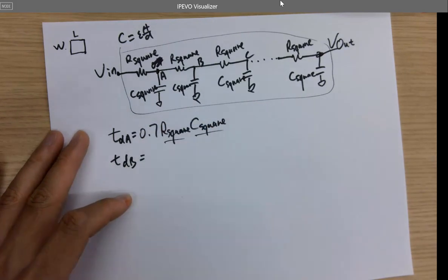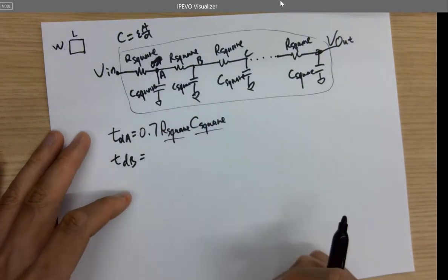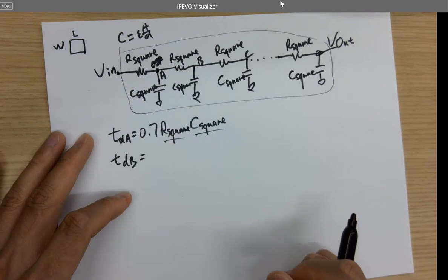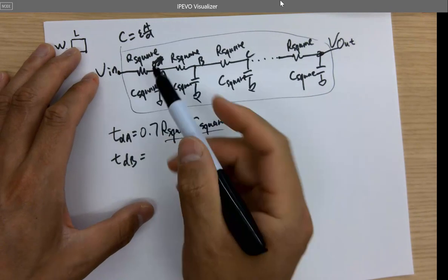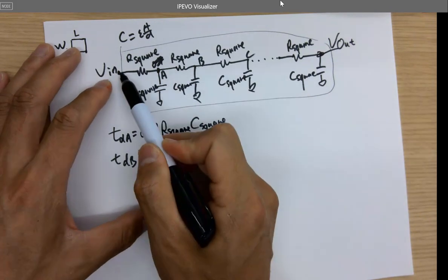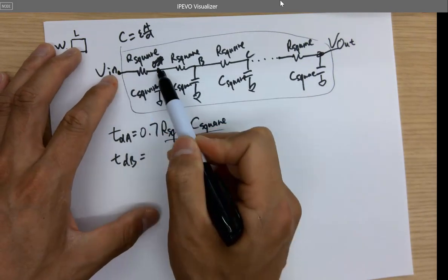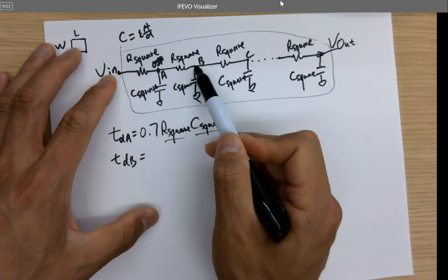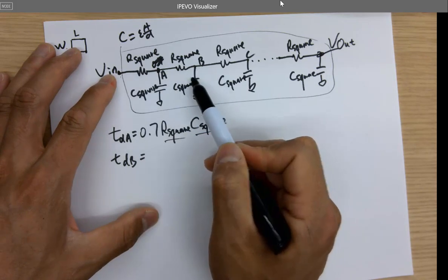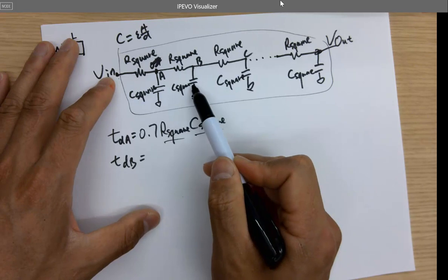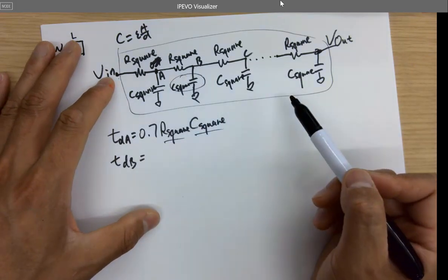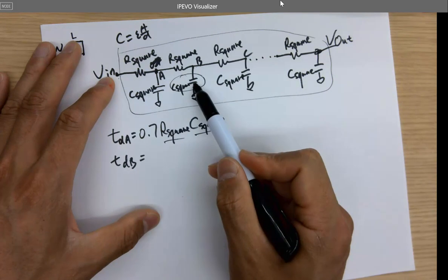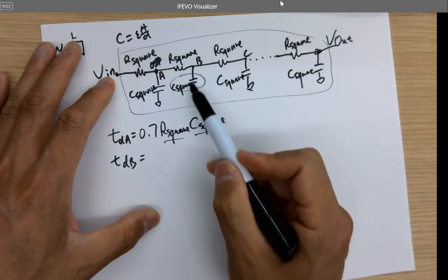TDB equals, no, actually the textbook did the way that you calculate it, because it's always from the input. So from input to A, you got a delay. Input to B, you got another delay. But only considers this cap, because only the capacitor is giving a nonlinear result, which is a delay here.